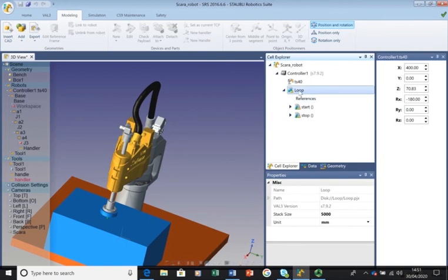Coming back, we've got our program area, which is a start and stop. We're not going to do any amazingly advanced programming, so what we tend to do is put all our code in the start area, but really what that will be is the beginning of a shift. Is this something that this robot needs to do only once at the beginning of the shift? You know, sort of warm up, check everything's there. Similarly, the stop is closing down. Maybe you have a gripper change and you want to put all the grippers back and then switch off the machine. But for us, we're just going to put everything in start.